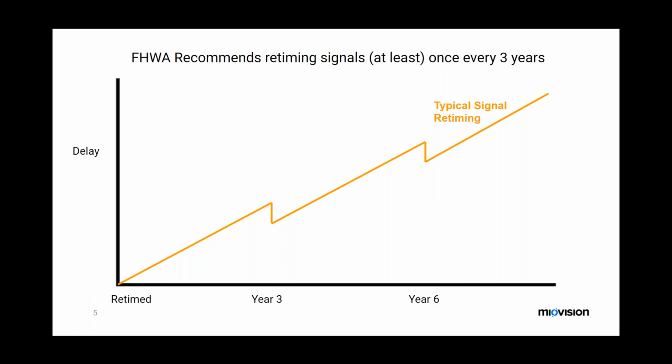What ATSPMs actually provide is a more iterative approach, a reduced delay. You can monitor it constantly, and you can make small tweaks to the timing over a longer period of time and make those iterations occur much quicker, so that the general delay of updates is much faster, and the public sees the signals change more appropriately, or change more alongside the developing road or the community, whatever it may be. So the whole purpose of utilizing ATSPMs is to decrease this delay in updating of timings and using real performance measures to make those changes.